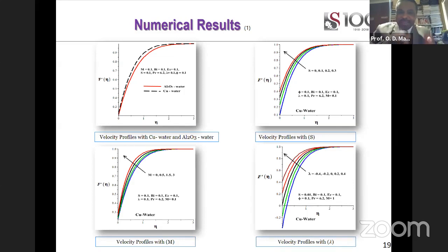So the magnetic field is there. There is a kind of electromagnetism taking place. There is a magnetic field generated there, which is imposed, and that is slowing down the flow rate so that the fluid does not just blow out. It touches the surface properly, takes out the heat and blows it out. Without a magnet to generate the imposed magnetic field, the cooling rate will not be efficient. So that is very, very important to take note.